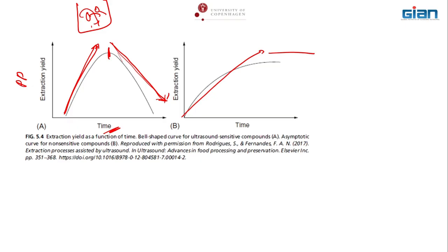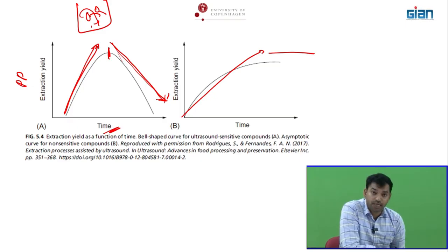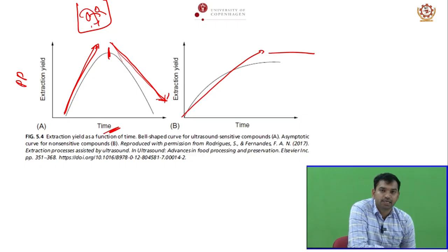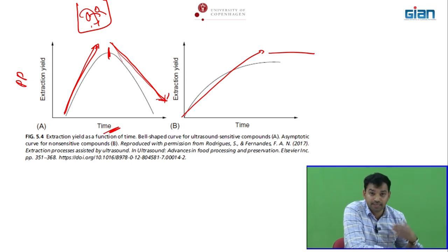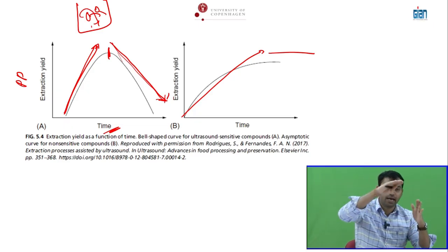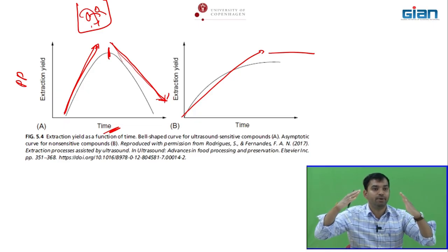Please note that people call ultrasound a non-thermal technique, but if you continuously apply it in a bath, you just see that the bath, you put your finger, right? It becomes warm and hot, right? Usually some biomolecules are highly sensitive to temperature and they can be damaged if you do a continuous ultrasound treatment. You increase the yield, yes, but you're also damaging them, because extraction and degradation go in parallel.